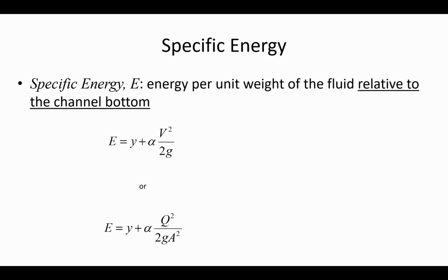if the flow rate is constant over time, and if you have that nice even prismatic channel that's not variable in its width and not variable in its slope, if it's just a uniform channel that never changes slope or width or anything about it, then Manning's equation is all you need. But if you look at the Ohio River, it's narrow here, it's wide there, it's winding, it has a bend, and the flow rate is always changing because yesterday it rained and tomorrow it's dry. So we need a way to predict what the depth is going to be with the real world variability in flow rate and channel profile.